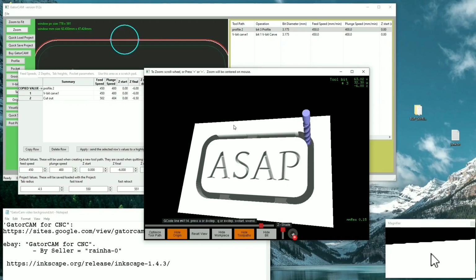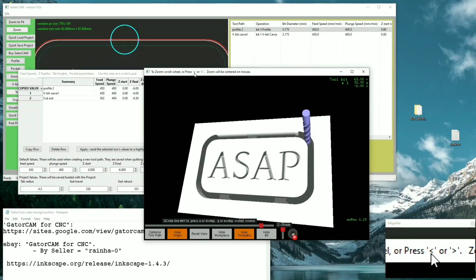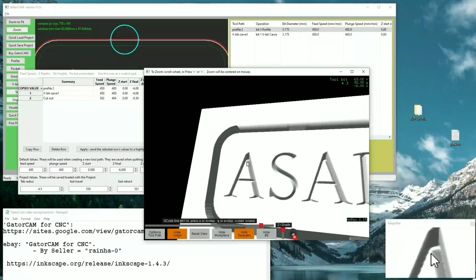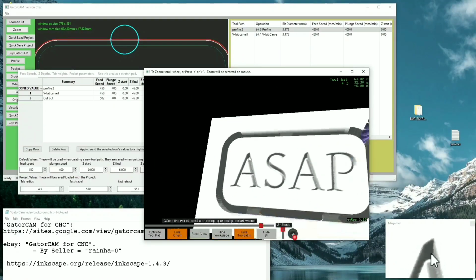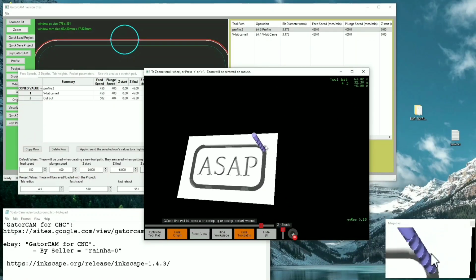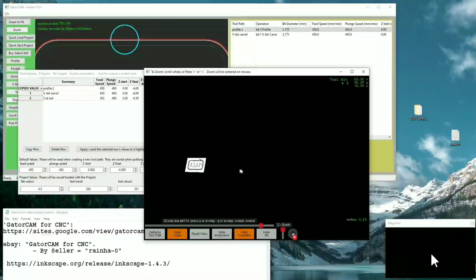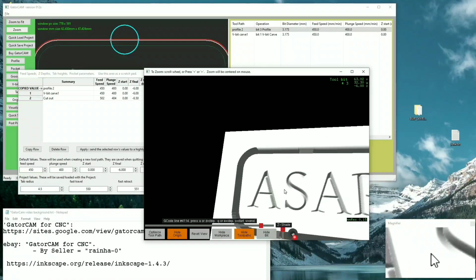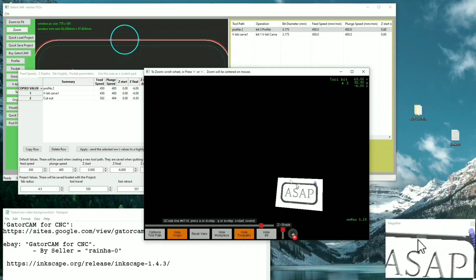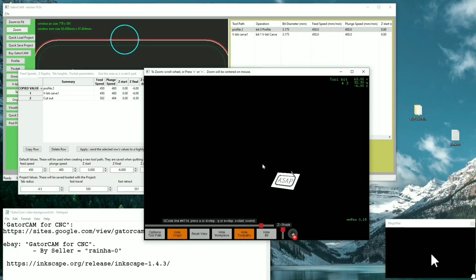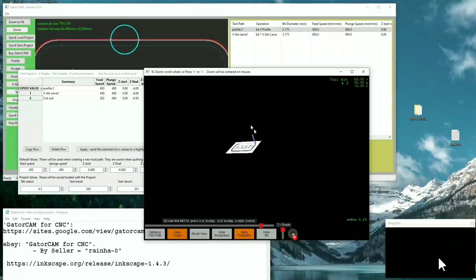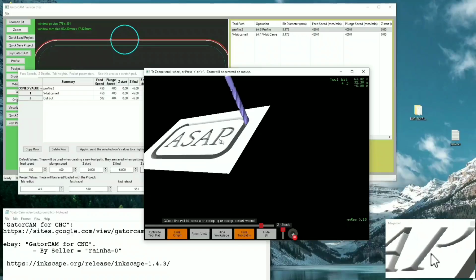But if you don't have a zoom key, you can use the greater than and less than keys. You don't need to hit shift on your keyboard and it'll still work. It might actually be faster sometimes to use the keys. And remember, it still zooms in on the mouse. So make sure to put the mouse where you want it to zoom in. And one of the cool things is you can also rotate it while you're zooming with the keys and use your mouse button to rotate.